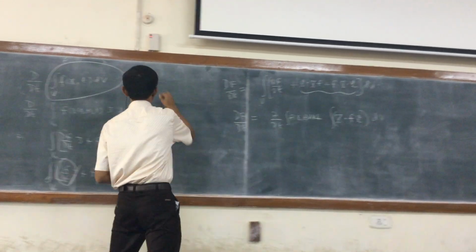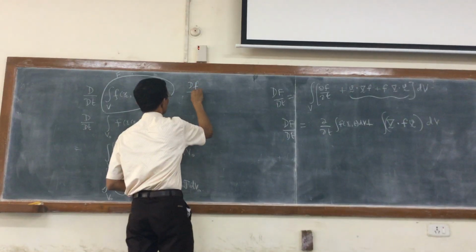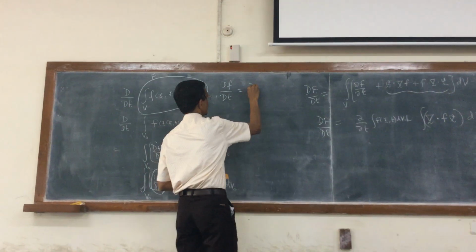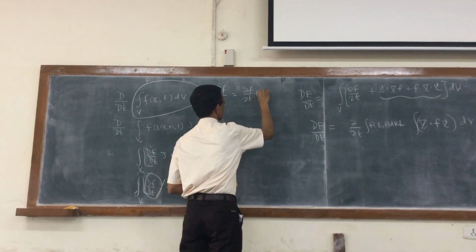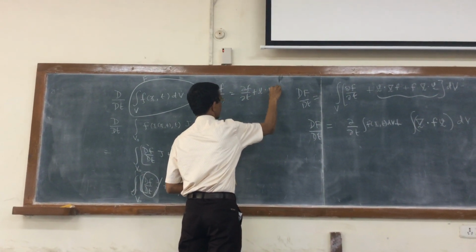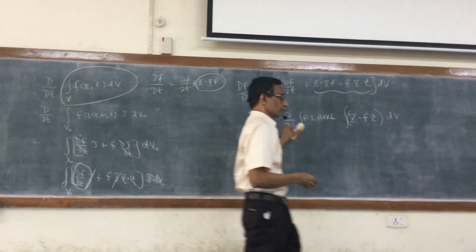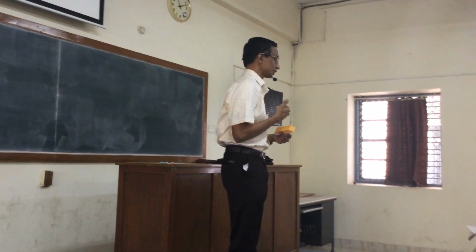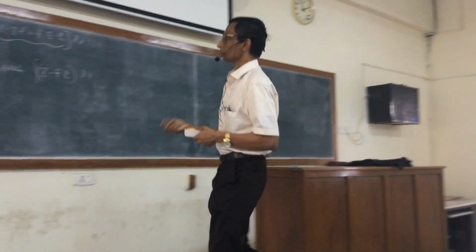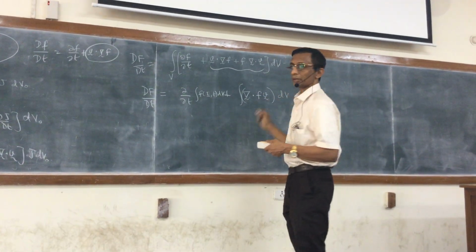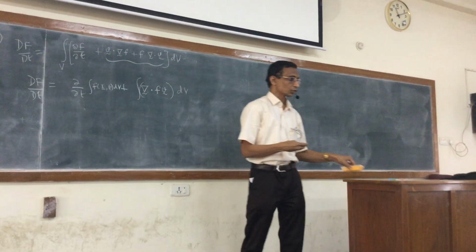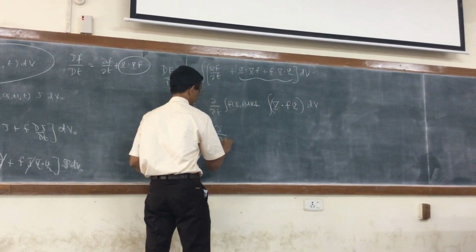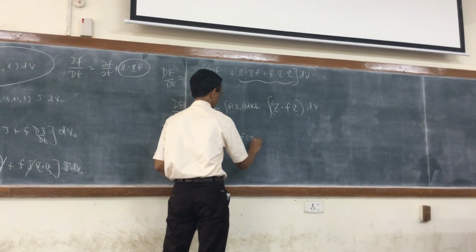We have to connect it with the earlier substantial derivative of simply a scalar function, not an integral, which is given by the spatial derivative of the scalar function plus an extra term. So for the integral, we again have the spatial derivative plus an extra term which can be expressed as a divergence of f times the velocity v. Further, using the divergence theorem, I can show, which again I haven't quite proved.